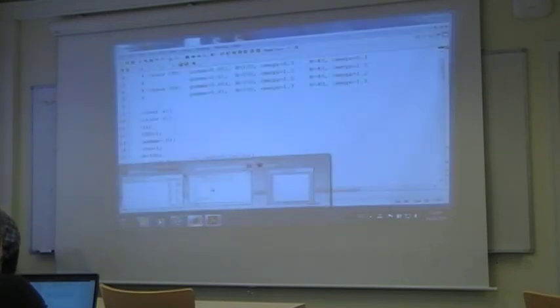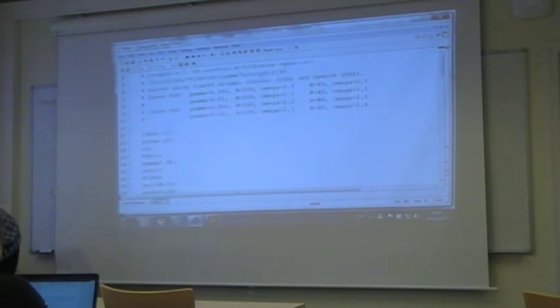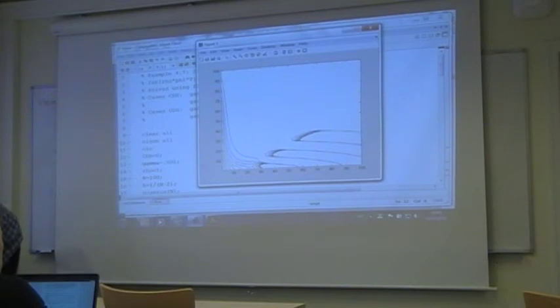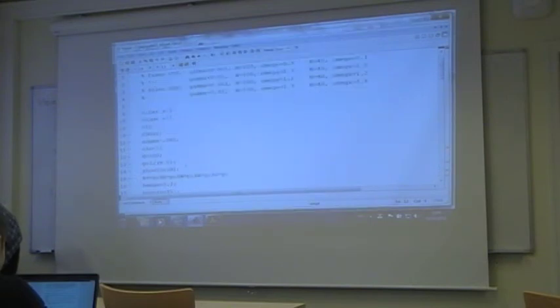The one to the right, that's now a smaller viscosity, gamma 1/1000. And now choosing an upwind. We should still make a solution here. No, it crashed. Nice image though. Let's try with a smaller omega.